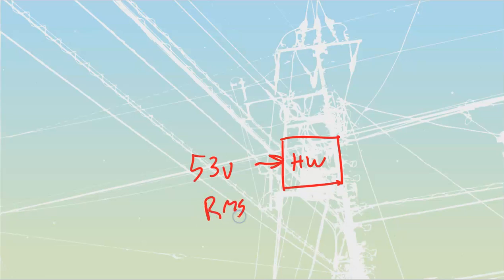We'll go back to what we were just talking about, though. We were just trying to work our way through the last calculation, which was a half-wave rectifier over here. And they're telling us that we're feeding into that half-wave rectifier with 53 volts. Now, if we're feeding in, that must be on my RMS side, right? And we're looking to get what my output is going to be.